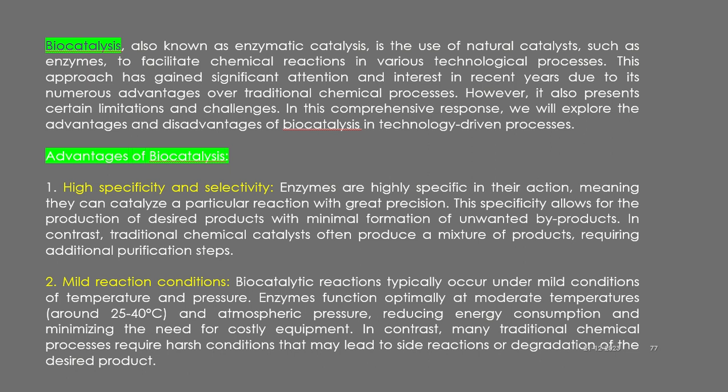If you are doing enzyme production on an industrial basis, it also requires certain pressure and a boiler requiring certain temperatures. Enzyme function can be operated at moderate temperature, in general between 25 and 40 degrees centigrade. If it goes beyond 60 degrees, it will be denatured. At atmospheric pressure, 1 atm, it works well.